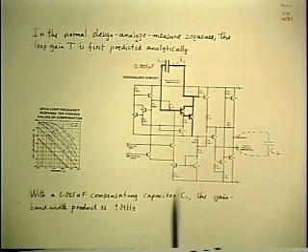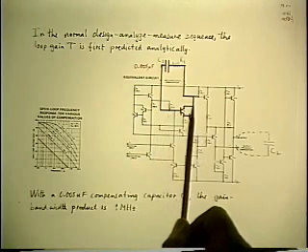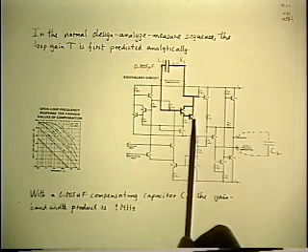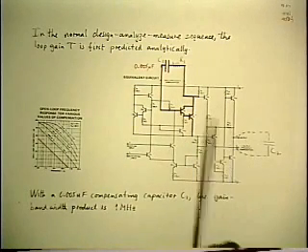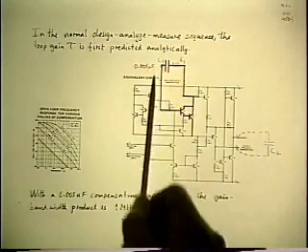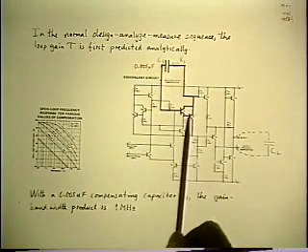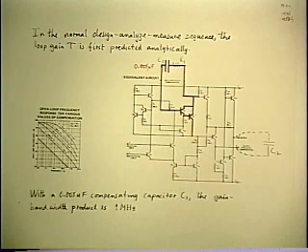Now remember, the reason you get a right half plane 0 is because you have a parallel non-inverting signal path that dominates at high frequencies, reversing the phase. And so when you put a limiting resistor in series with it, you limit the gain of that path to be less than the gain of the other path, so it doesn't take over. So you don't get a right half plane 0. And that's the reason the resistor ought to be in there.